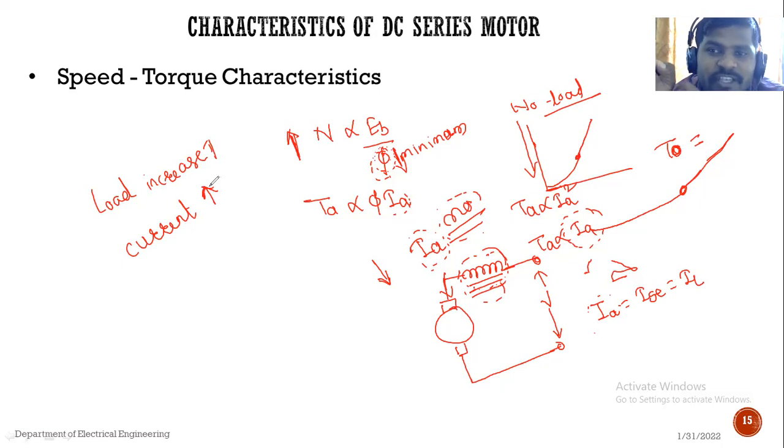So one precaution should be taken: a DC series motor should never be started without load.